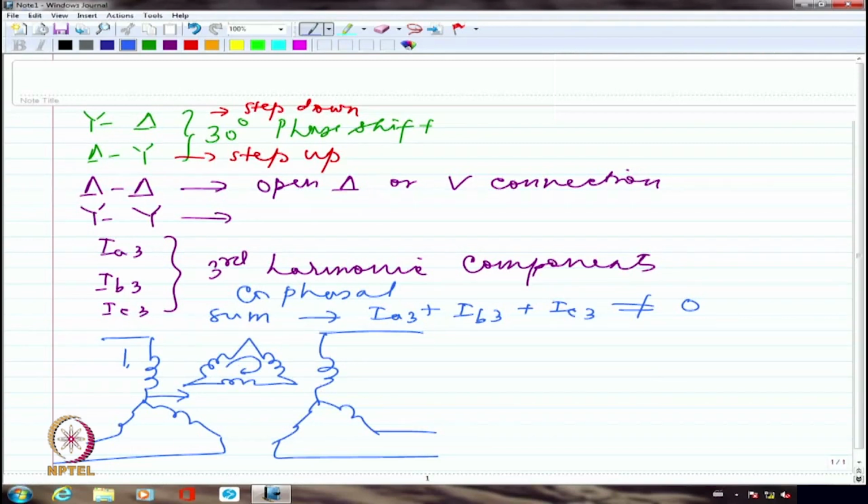That's all we are doing. Nothing else. Right? So please understand that any current, if it flows either in the secondary or in the primary or in the tertiary, it can cause a voltage drop or voltage induction in the other coils as well, because they are all mutually coupled. So very clearly, if I allow the current to circulate even in the tertiary, it is definitely going to have repercussions on the induced EMF on the primary.